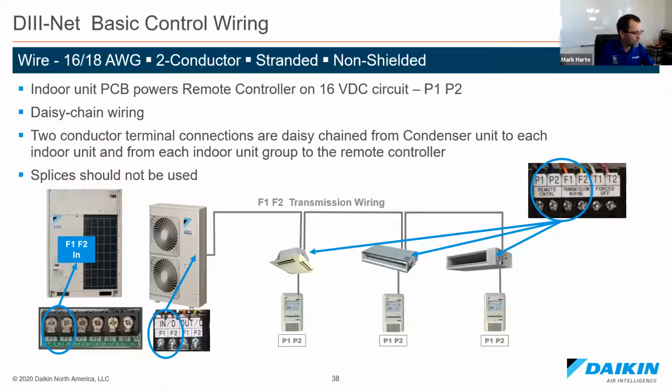So it's just showing you here the same thing I showed you earlier, the wire connections. Now that's a VRV. That smaller unit to the right there is a VRV4S. That doesn't come in heat recovery. It's in heat pump only. It's like commercial residential, but it has the same communication leg, and you can use all those fan coils I just showed you also on the VRV4S. It's not limited. It's the same fan coil, same indoor units. Of course, less capacity because the largest this comes in is a 5-ton unit. On the heat recovery and heat pump, I think we go up to 38 tons or 42 tons, depending on what you manifold together. Like I said, it's a smooth daisy chain we want, and no splices.